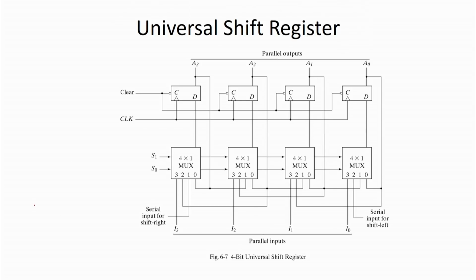If I say that I am having a 4-bit register, then we are storing 4 bits of information, and whenever required, we take it to the output lines, say A0, A1, A2, A3. What is there in this register? Basically, we have 4 flip flops. According to our requirement, we store the information in the flip flops, and whenever required, we take this information out.